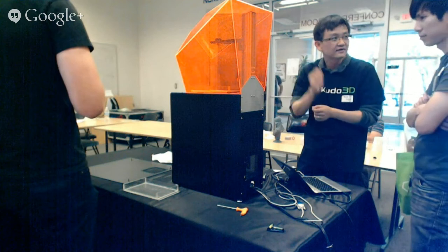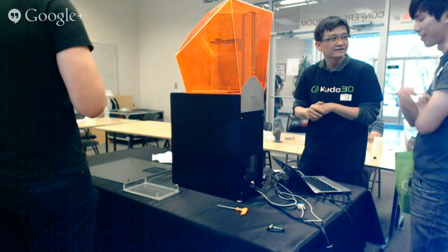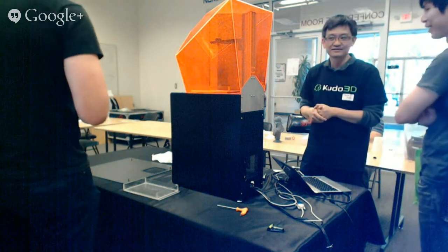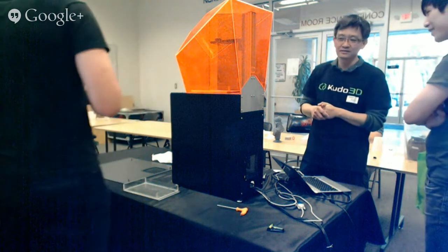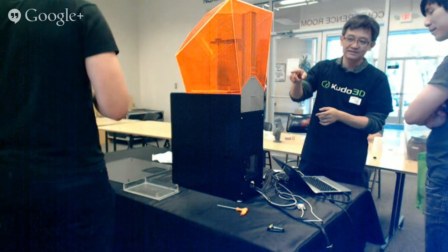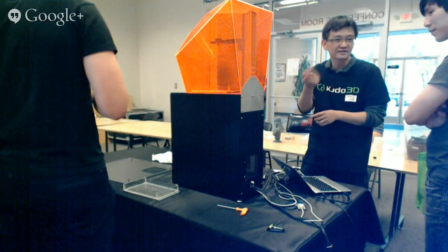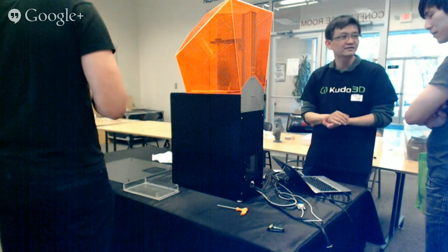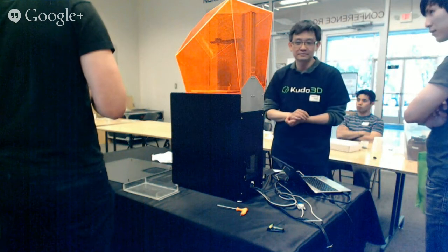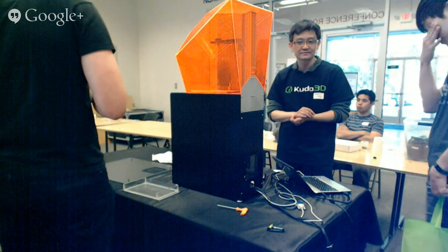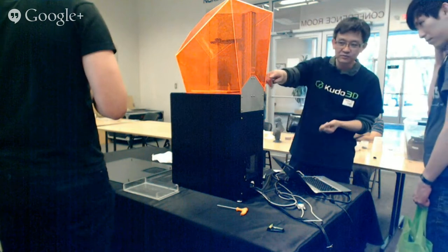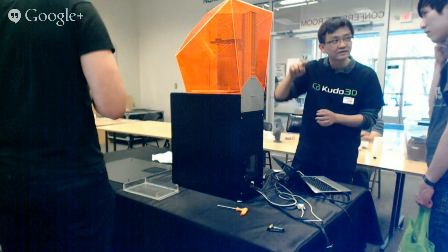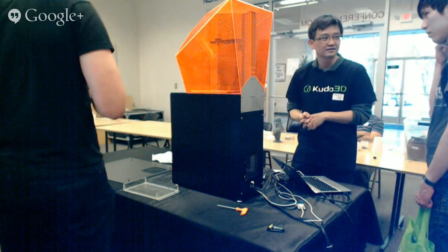Then all the different warpings that you get, warping like this, is very non-linear on this face, right? The chance of this face coming out perfectly flat doing a traditional SLA way is virtually impossible, right? And I know that the flatness of these surfaces is paramount, especially this one. This doesn't meet the other side of the mold. So this working mold will have crazy ejections in the filling, right? So I really need this surface to be flat.